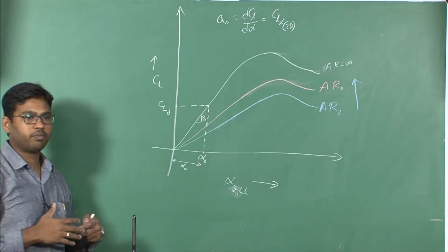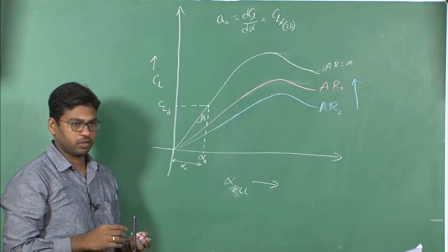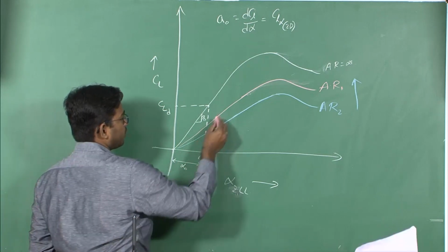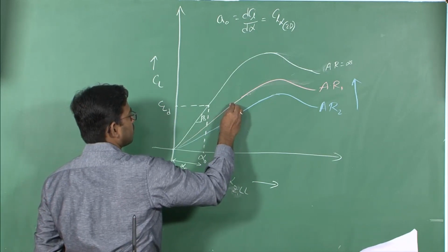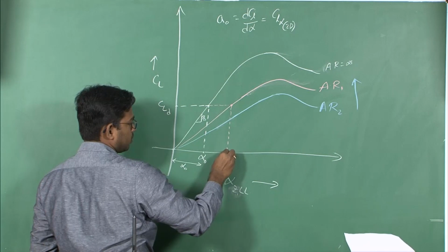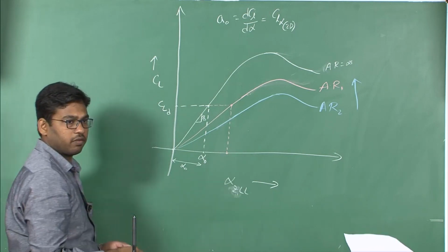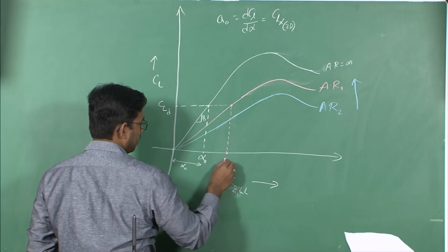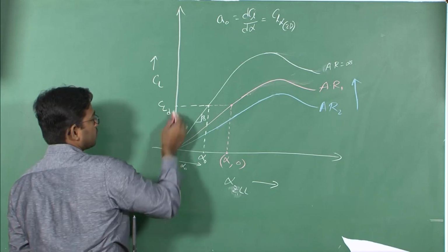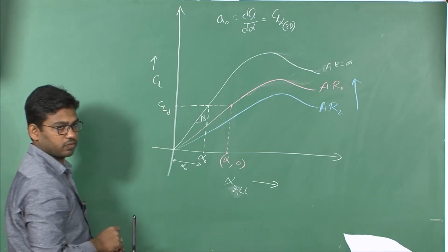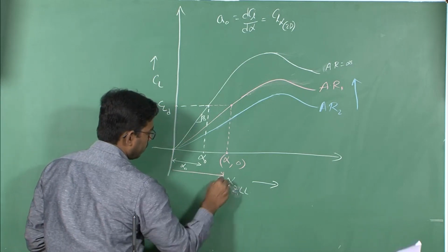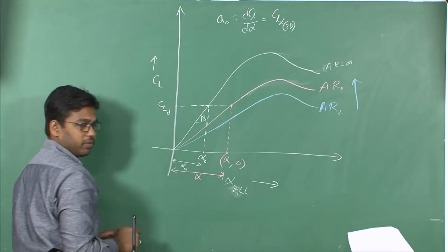Now let us assume we have built a wing using this particular aerofoil without any geometric twist or aerodynamic twist, right. Now what happens if I want to achieve the same CL here? I need to trim the aircraft at an angle of attack, let us say this be alpha. This point represents alpha comma 0, so this point represents 0 comma CL design, okay.